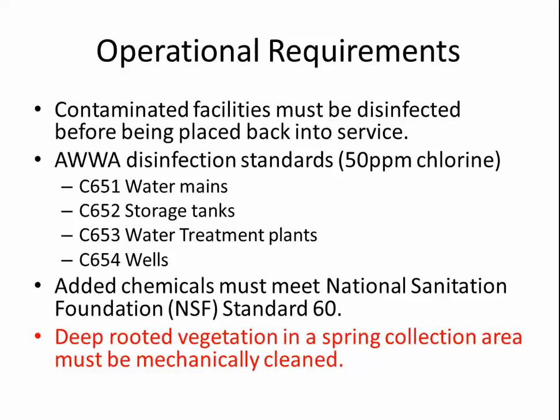awwa.org. Something that is also important to know is that anytime you add chemicals to your water supply, those chemicals have to meet the NSF standard 60. And something that's good to remember if you're taking the operator certification exam is that NSF stands for National Sanitation Foundation.